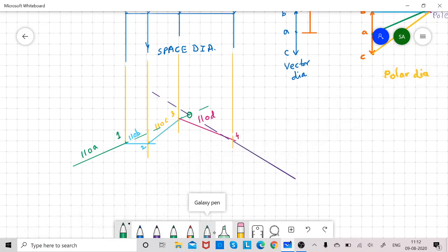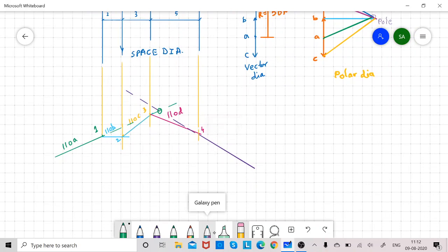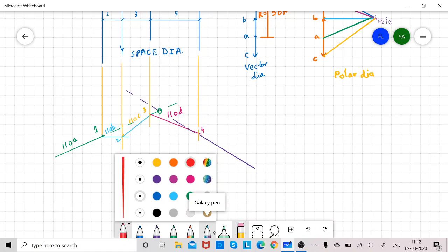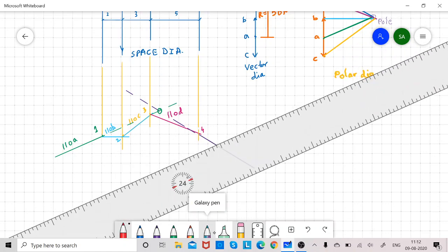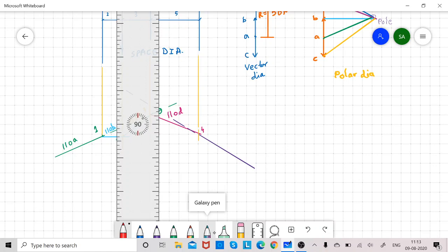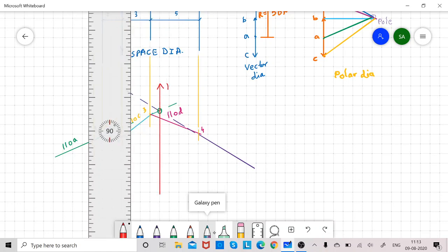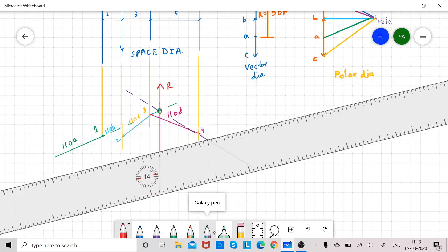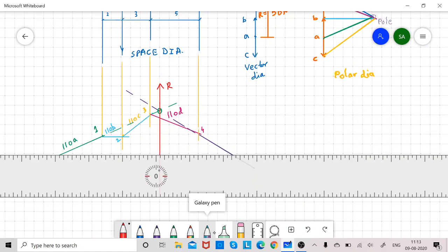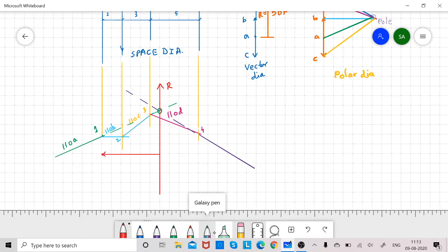This point is important because through this point the resultant, which is 50 Newton upward, passes. So this is the upward resultant R, and its distance from, say, the first force: just measure this length from the first force, and as 1 centimeter is equal to 1 meter, convert it.